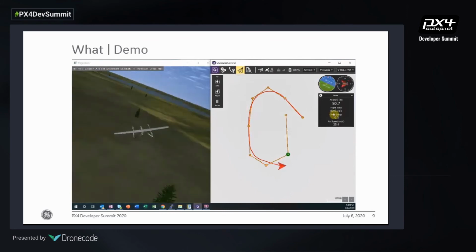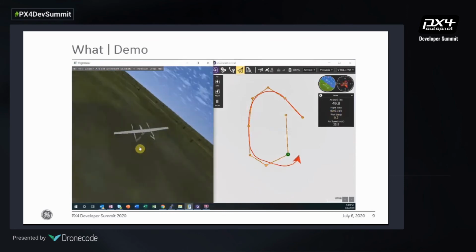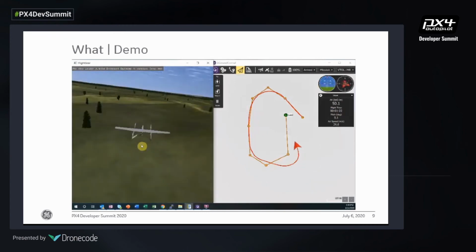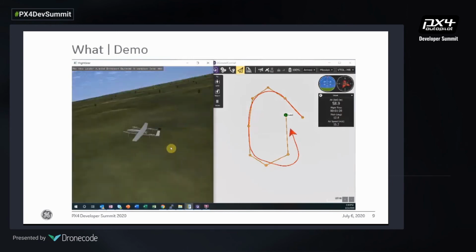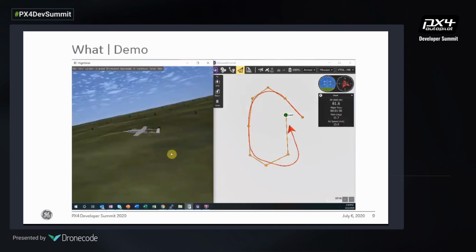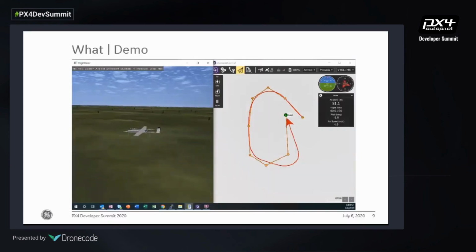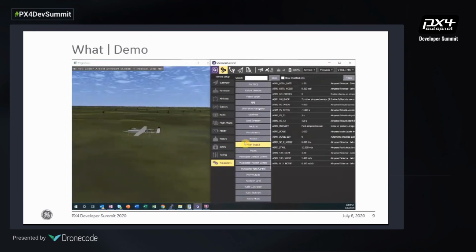So kind of talk through most of the flight, but as you can see, we're going to loiter around this waypoint to line us up for approach as I change the perspective. And here we are doing a back transition. It's also helpful to understand in the simulator how long, from a distance perspective, the back transition would take, as the particular vehicle we modeled likes to fly, and so we wanted to have a good understanding of where that back transition would finish.